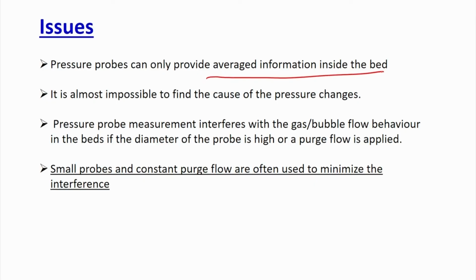The only problem is you cannot say anything for concrete, it is all global, okay? It is not local information. So, it is good to get a first hand idea, but if you want detailed characteristics of the flow, then it cannot be used for that purpose. So, that is the major issue, that it provides the average information inside the bed, it does not provide local information, and as we discussed earlier, if the reaction is very fast, then the local dynamics plays a major role compared to the overall dynamics. Okay. So, that is the major disadvantage of this.